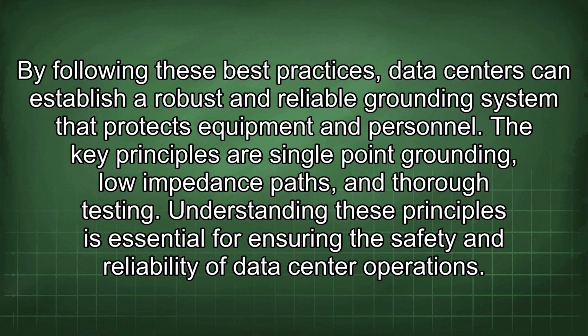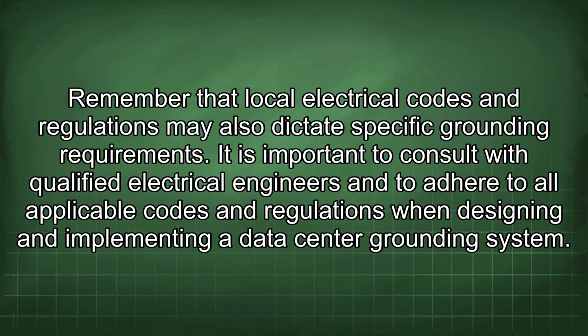The key principles are single-point grounding, low impedance paths, and thorough testing. Understanding these principles is essential for ensuring the safety and reliability of data center operations. Remember that local electrical codes and regulations may also dictate specific grounding requirements. It is important to consult with qualified electrical engineers and to adhere to all applicable codes and regulations when designing and implementing a data center grounding system.